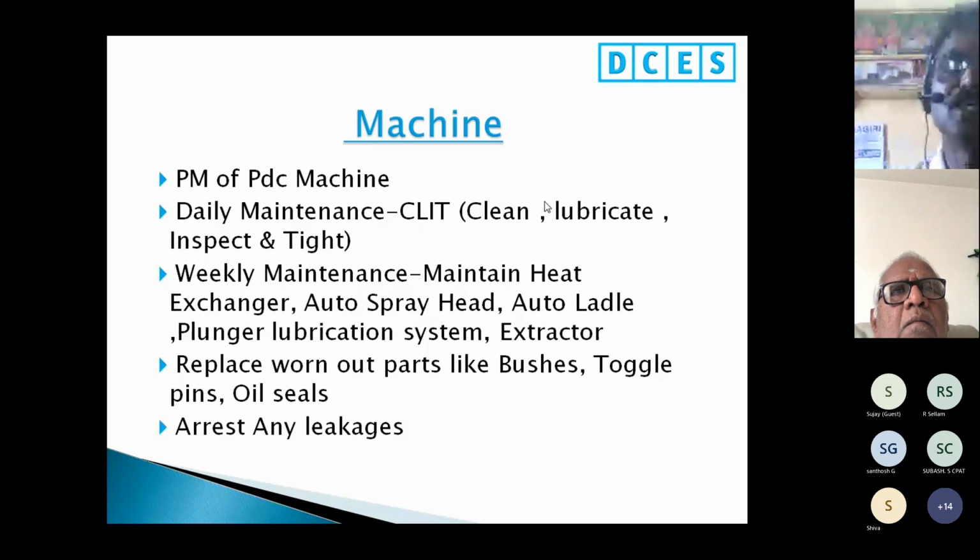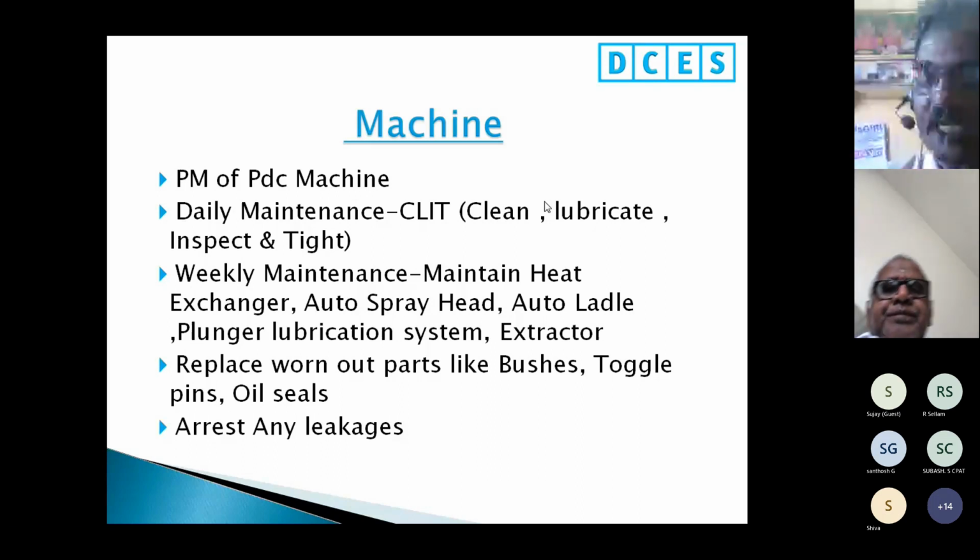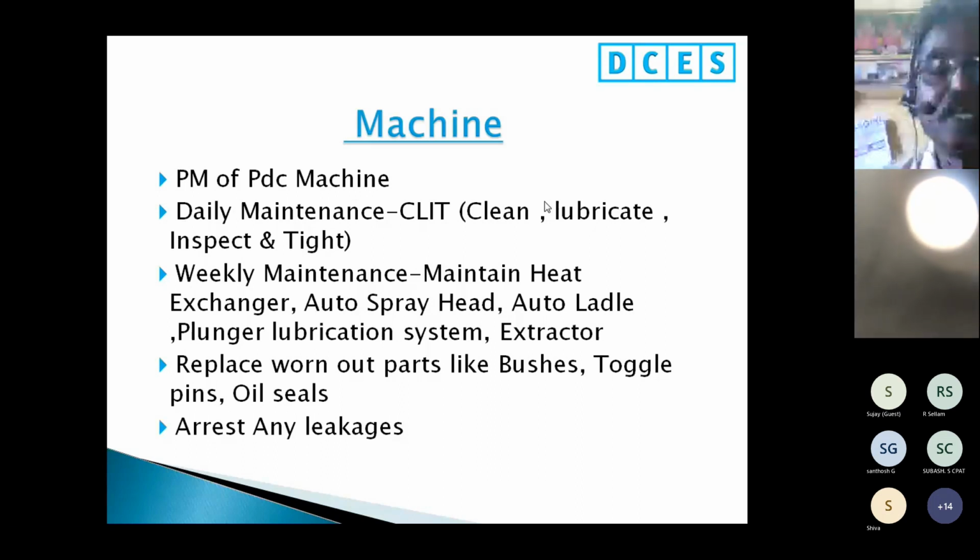Replace the worn-out parts like bushes, toggle pins and oil seals without fail. Arrest any leakages. Any leakages in the machine, oil leakages or water leakages, should be arrested.